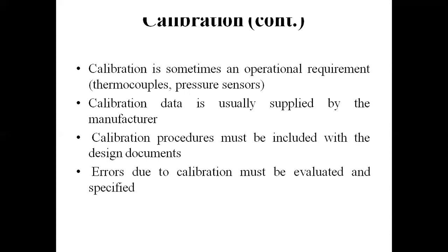Same order of accuracy. Okay, so the instruments which are calibrated directly will be named as direct calibration. Whereas in the case of indirect calibration, the procedure is based on the equivalence of two different devices adopting some similarity concept. Okay, so these are all about the sensor calibration. So calibration is just a set of operations in order to establish the relationship between the values that are indicated by the measuring instrument and the corresponding known value of a measurement.